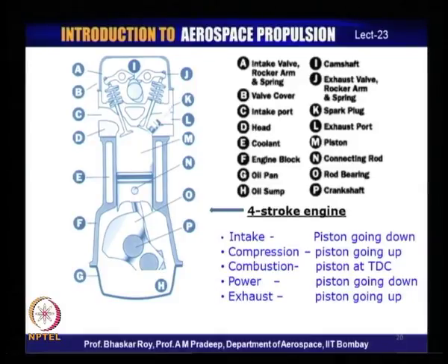Let us quickly understand how the thermodynamic processes are converted to what we call now strokes. The familiarity of the engine, very quickly, we have an intake valve over here, which opens this intake port through which the fresh air comes in, and there is a timing given. So, this has to be timed properly, and air comes in through this and fills it. So, when this is at the bottom, what we call BDC, and the piston is going down in the intake process, this entire space is now filled up by the air coming in from here, and this valve is open.